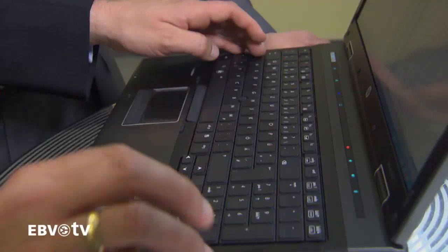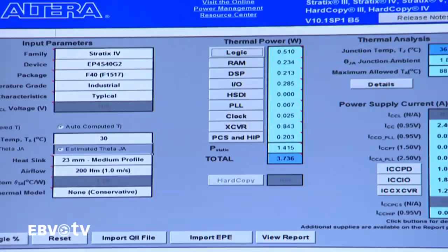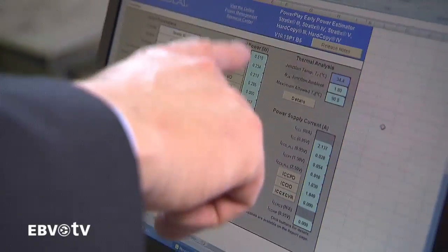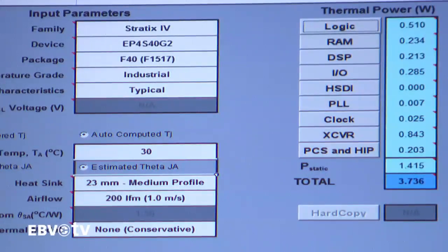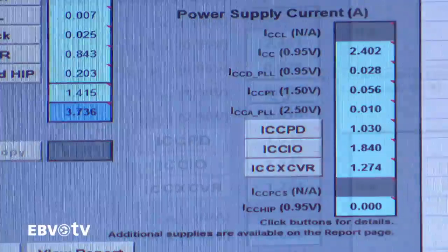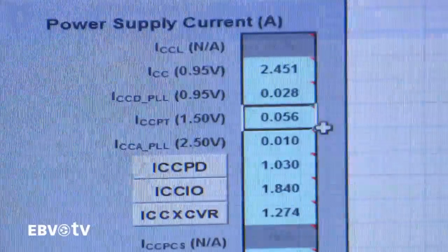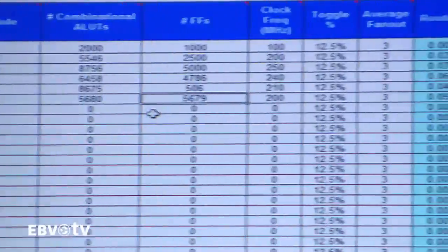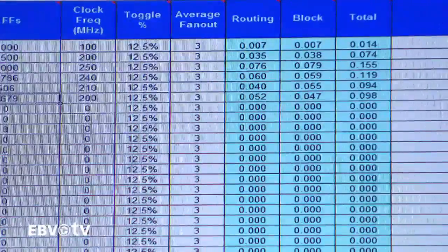Due to the complex voltage requirements of the state-of-the-art FPGAs, the manufacturer provides a tool to calculate the estimated power consumption of a given design. Users can select the device they are interested in and specify the design features. The tool provides the required voltages and the respective currents. Using microcontrollers and ASSPs, this information can be found in the device's datasheets.